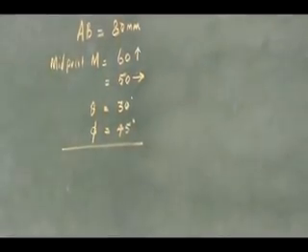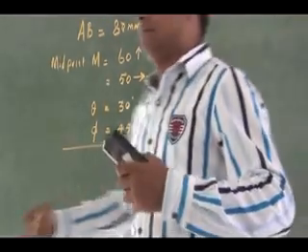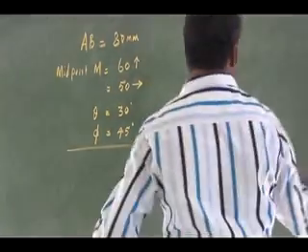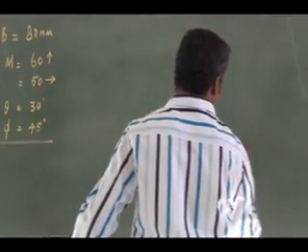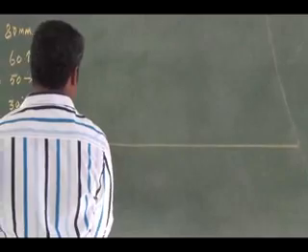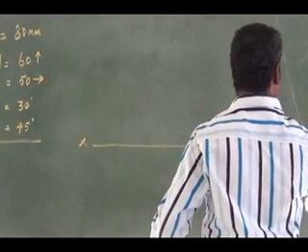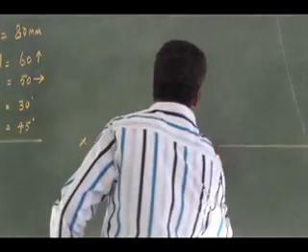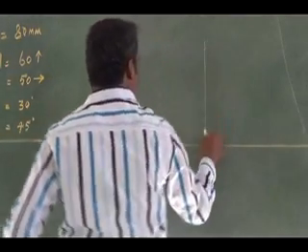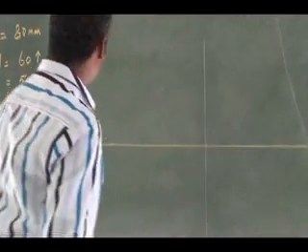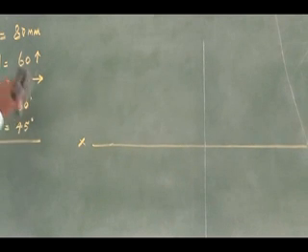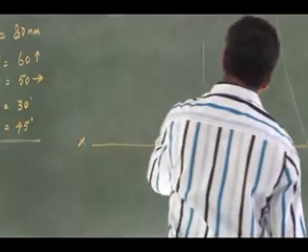So what is it? It is similar to the very first both-side inclined problem. Instead of an end, you have to project a midpoint. Draw the reference line as usual. So this is my X, Y, this is VP, this is HP. Instead of one end, I have a midpoint projection. Draw a projector in the middle to project the midpoint, 60 mm above HP and 50 mm in front of VP. So it is 60 mm above.